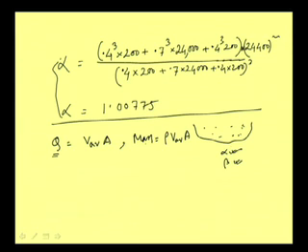For calculation of mass, do we need any coefficient here? We do not, because the very basic value of V average that we are calculating already considers the variation of velocity. Through area we are calculating individual discharge, we are summing up the total discharge, then we are dividing it by the total cross sectional area. So, here we do not require that.